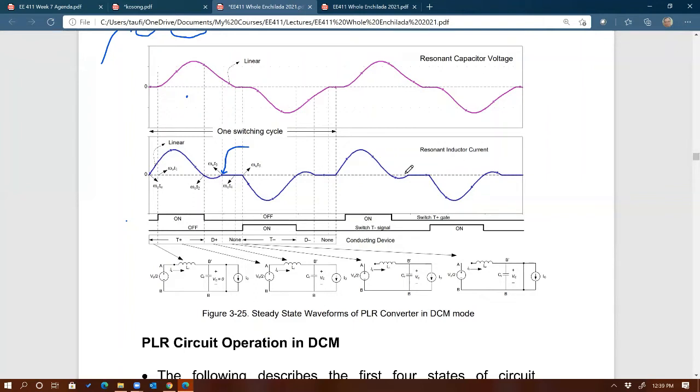It doesn't have to be a Schottky, which is a good thing, because this converter is typically used for high power, high voltage. If you are dealing with a high voltage converter, it would be nice to be able to use high voltage components. And Schottky's, I mentioned this last week, the highest rating I've seen is 250 volts.